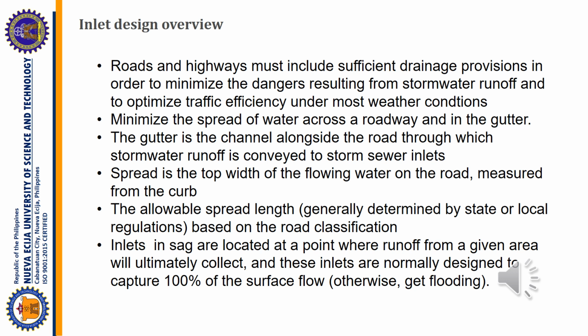Kumbaga nasa isang flow lang po sila. The gutter is the channel alongside the road through which storm runoff is conveyed to storm sewer inlets. Number 4. Spread is the top width of the flowing water on the road, measured from the curb. So yung pagtaas nga daw po ng tubig is pwede nating ma-measure sa curb.